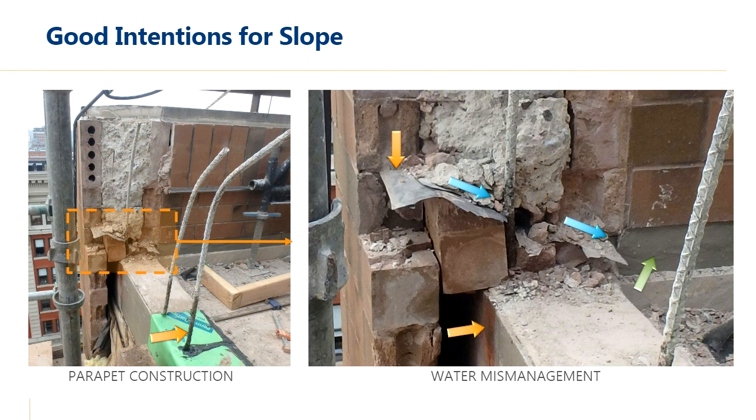And so as the water came down, and you follow that blue arrow, it's following that rebar down, and you can see the good quality of that rebar where it was embedded in the concrete, as opposed to the corrosion that's happening below. That's a little more apparent on the image on the left with the orange arrow, but coming back to the right, you can see some of the staining that's occurring on the other orange arrow at the bottom, where that rebar is corroding.